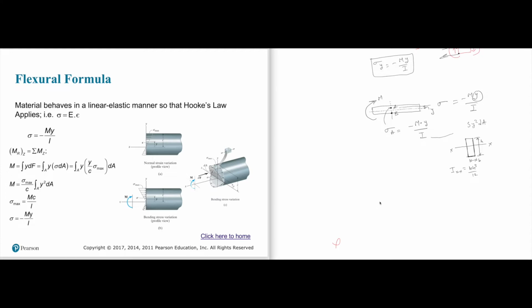You don't need to remember the formulas because I will give you the formulas, but you need to know how to apply them. Listen to this important thing. Moment of inertia with respect to different axes is different. For example, moment of inertia of this shape with respect to xx is BH cube over 12.